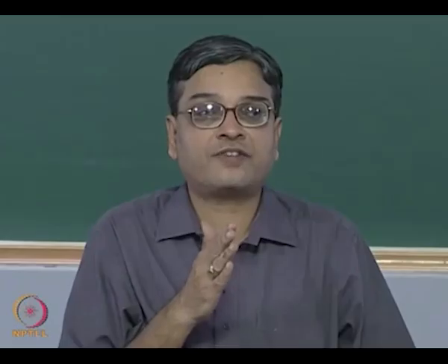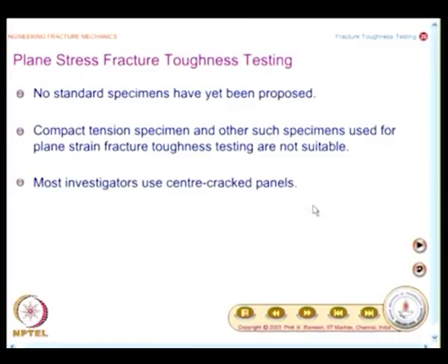And another important aspect we had looked at in plane strain fracture toughness was you have to develop a natural crack. Only with a natural crack can you conduct the testing. That was a big circus. You had seen the chevron notch, and we also saw why the chevron notch was used. It is to have control on the origin and the plane of the crack for you to have a comfortable specimen. Then you had fatigue pre-cracking restrictions and so on and so forth.